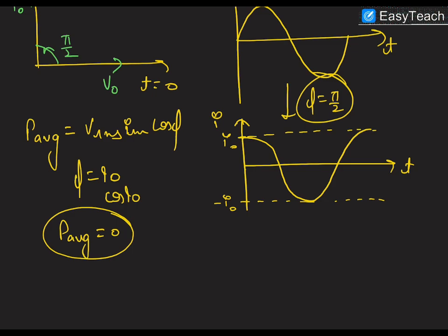Okay, and this is the important fact, and therefore we can say that the RMS current flowing in the pure capacitive circuit is in fact wattless current, because it does not contribute to any power loss. Therefore, we call such current wattless current.